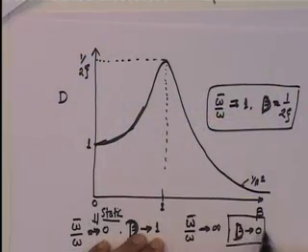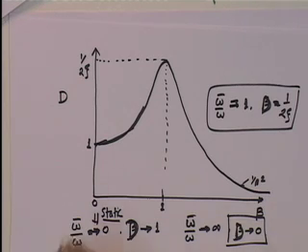So, when the excitation frequency is very high relative to the natural frequency, then the dynamic amplification factor is 0. What does that mean? There is no response. That is very interesting, isn't it? There is a loading, but there is no response. Okay? We will come to this. I will explain the physical aspect to this shortly.